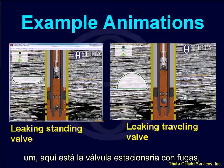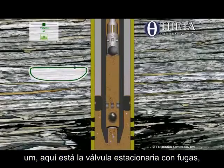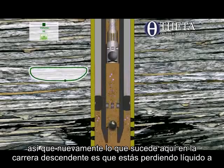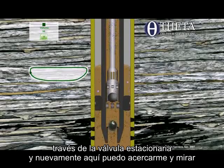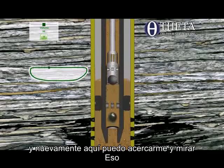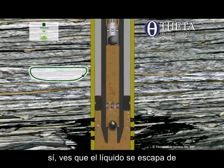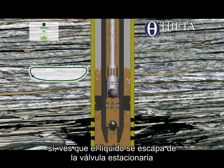Here is the leaking standing valve. So again, what happens here on the downstroke is that you're losing fluid through the standing valve. And again, here I can zoom in and look at that. You can see the fluid leaking out of the standing valve.